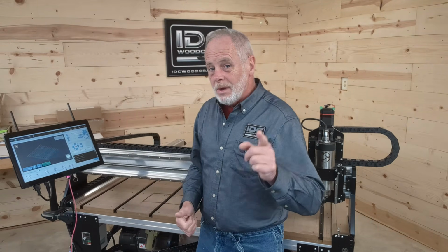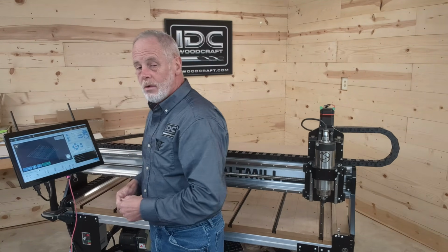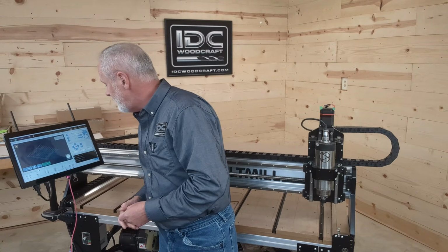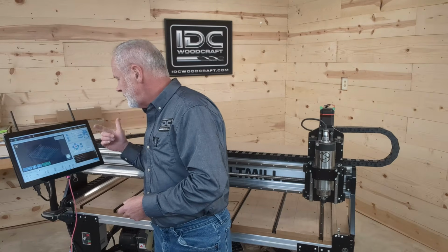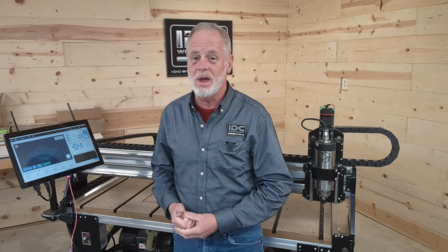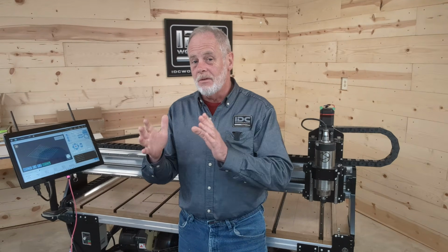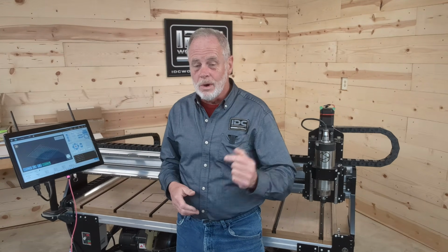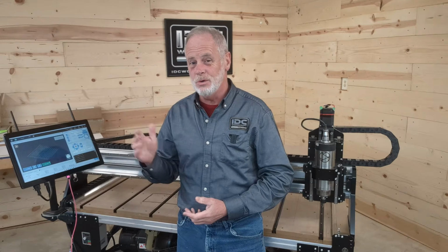What you do now is just read the numbers off of your readout here. Mine is 49.055 in the X direction and minus 49.055 in the Y direction. So that is the max travel of my Altmill CNC router. And I'm going to use the 49 by 49 when we get into designing our grid. And so will you, as you will see.